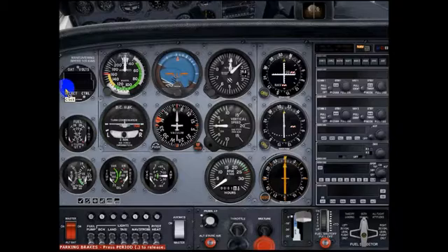Anytime you fly an airplane, you have to make sure that the pilot operating handbook associated with that aircraft, with the weight and balance data, is inside the aircraft, or it is not legal to fly. Let's jump into limitations first. Never exceed speed. It's 160 knots.